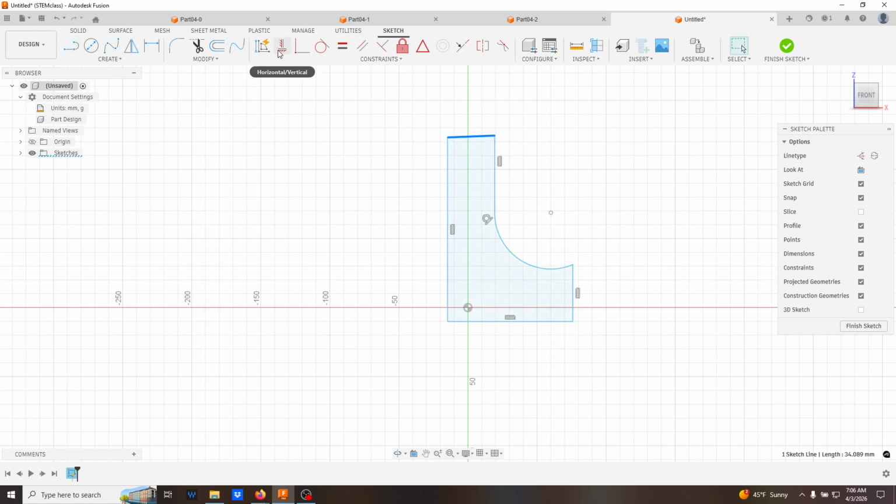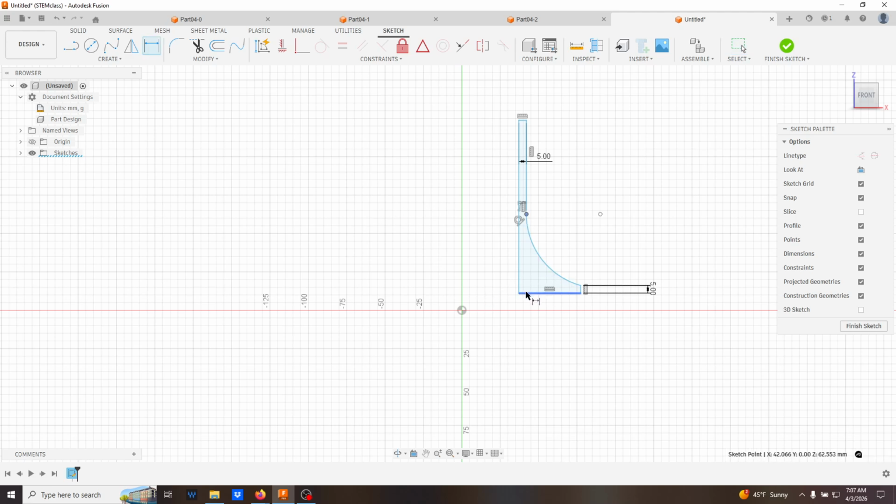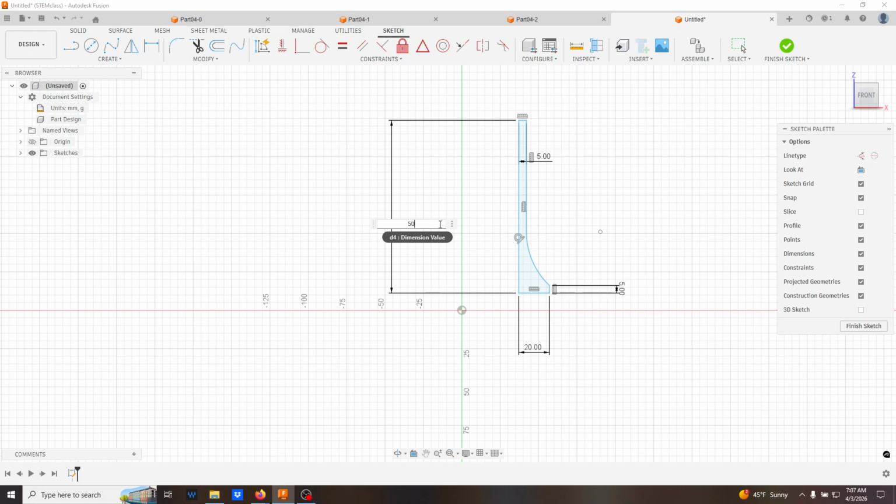So a lot of times when I'm drawing and I know the dimensional relationships I want to establish, I'll do exactly what you saw me do here. I'll draw my baselines with constraints turned off. And once I get my joined relationships, I'll go back and add the constraints that I want, because again, it covers the design intent and the exact relationship I want between the objects I am drawing.